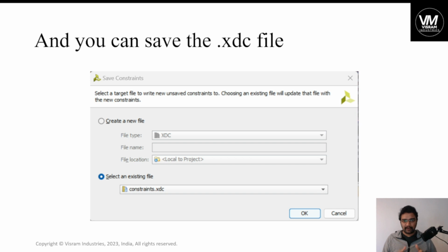Sometimes in the design process, you will be keeping two constraint files, before IO planning and after IO planning, because when you have done a wrong IO planning, you can delete this file and you are not interrupting the original constraints file. That is an ideal practice. But as of now, I want you to overwrite on this one. But it is a best practice to save your original files. Again, another tip as an engineer: you need to save the primary source files every time as a backup.